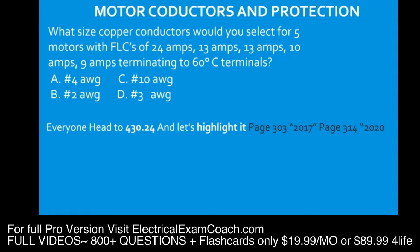Okay, so when we get to 430.24, we're going to read the black gold heading. It says several motors, okay? So what we're dealing with is when we have more than one motor. First off, I want you to highlight in the black gold heading the words several motors, if you're allowed to highlight in your state. Then go down to part 1 and highlight 125%.